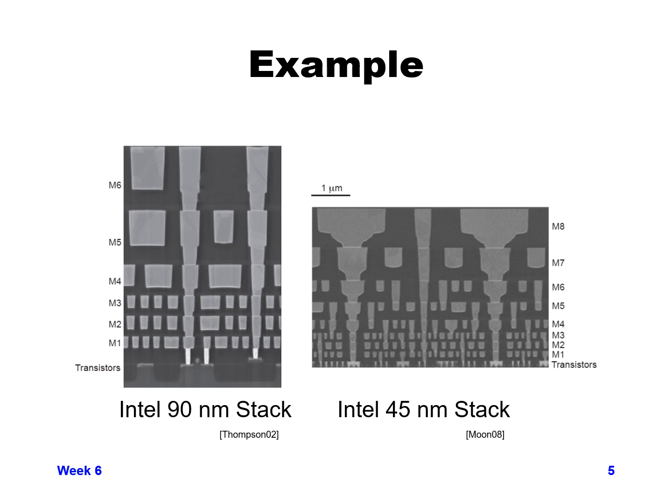Currently, we're around the 10 nanometer area, and like I said, up in the 12 plus metal layers is typical for 10 nanometer, and going on to 7 nanometer, depending on which foundry you're going to, might even go beyond 12 or 14 metal layers in the near future.